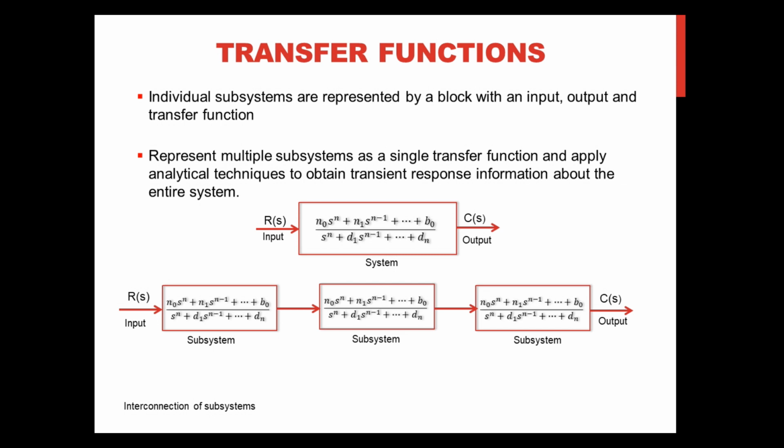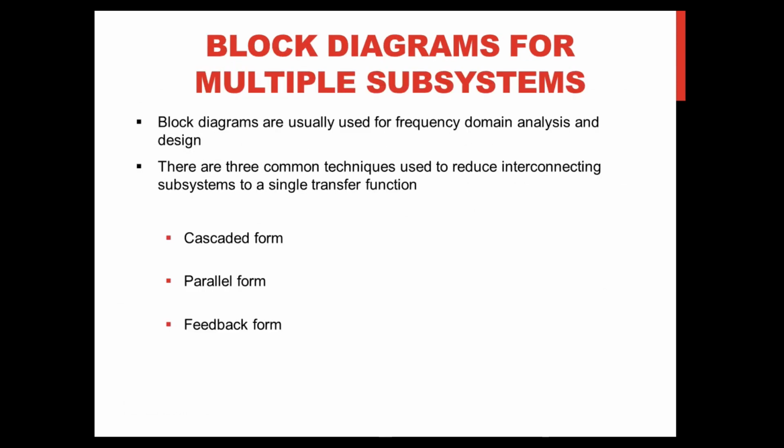Since the response of a single transfer function can be calculated, we can also represent multiple subsystems as a single transfer function and apply analytical techniques to obtain transient response information about the entire system. Block diagrams are used for frequency domain analysis and design.